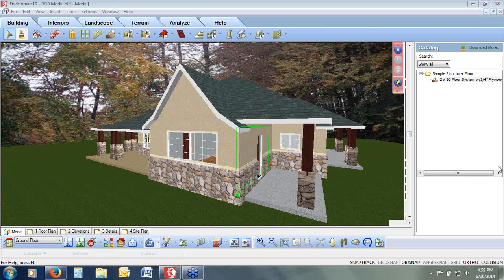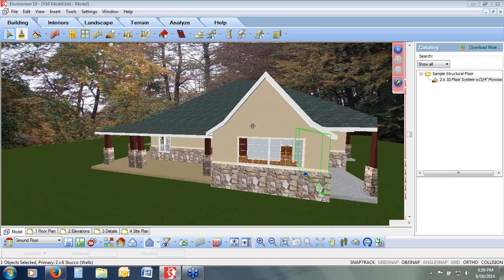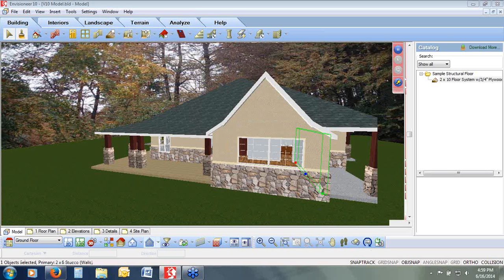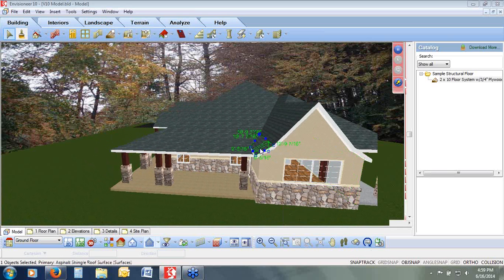I may need a 6/12, a 10/12, and a 12/12 gable roof pitch for my project. Would I have to change the default hip program for all 3 gable pitches? No, you can just insert it. You can notice here on the sample model that I'm using today, it has a double slope. So I have, I believe, an 8/12 going to a 14/12. I just put it in all as an 8/12 and then just did that on the one side here. And this is something that you can do in your current version. This isn't something that's new with version 10.